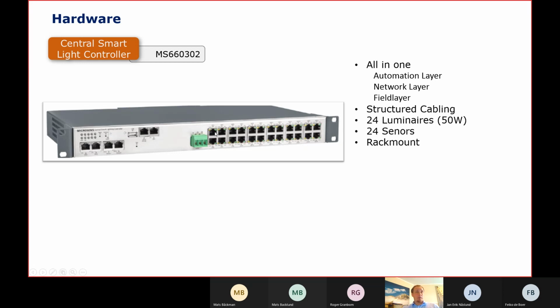So the same wire used for network, we can now also use for powering the LED. But this is not a real network port anymore. This is just the output with the 2 wires separated from the 8 wires of a CAT cable. By doing so, we have 24 luminaires. We just need a plain power supply and have a standalone device. It can operate standalone, but with the benefits of having our automation layer with a user interface, controlling of light, and many more features, like a PLC can also be installed here. It works standalone, or can be stacked with multiples of those, without depending on PoE.